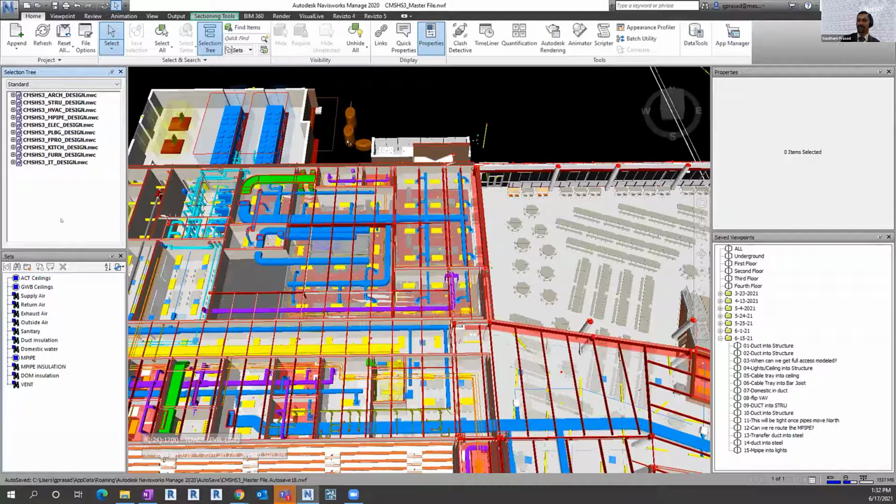And first of all, I do want to tip my hat to Scott for acknowledging that Navisworks is great and the cloud doesn't replace it. We love Navisworks. Again, I'm a general contractor. I'm a VDC manager, and we use Navisworks primarily for coordination with subcontractors. And we get down to 3/4 of an inch or less where we get really tight. And we need the flexibility and the navigability of Navisworks, being able to section all day long and move stuff around, measure between things. It's just great. We love it. So normally what we're doing now is not coordination, it's design review.